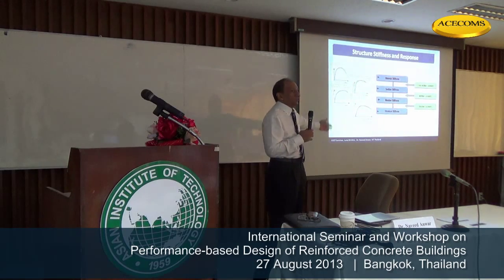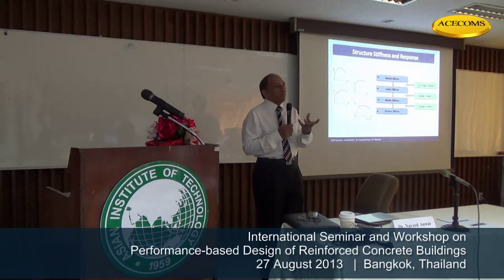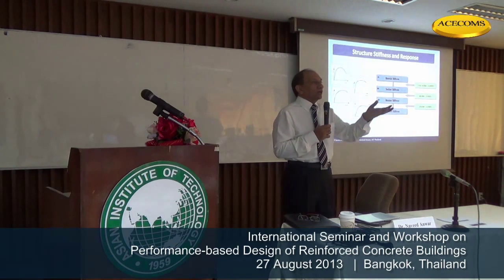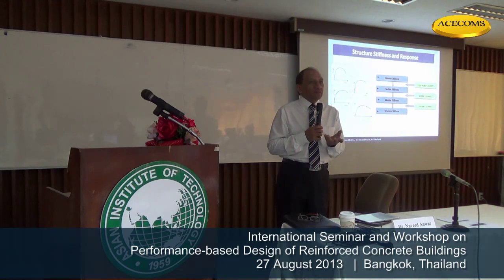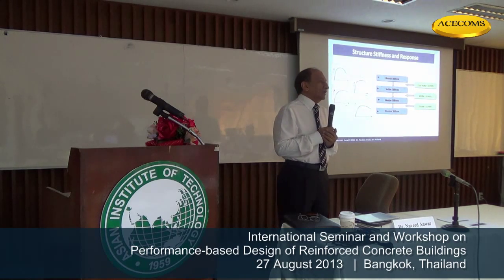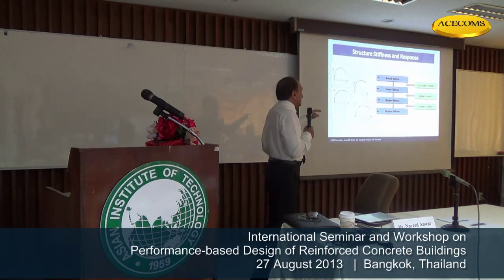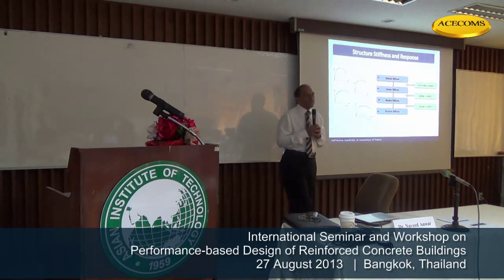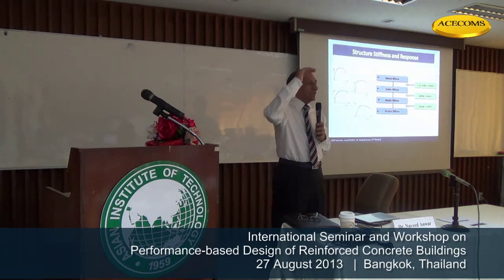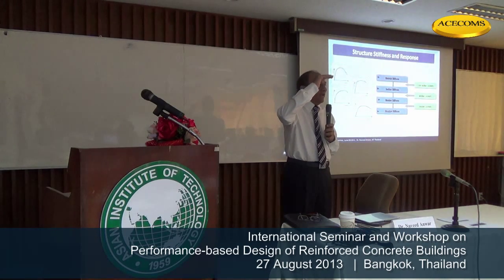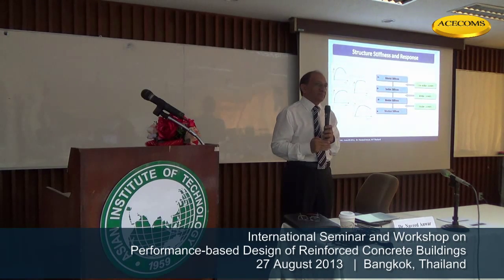Then you have structural stiffness, which is a summation of many members. But some members are collapsing during deformation. Some are becoming ineffective. So the structure is also nonlinear. So structural stiffness K that we saw in the previous equation is highly nonlinear because 4 levels of nonlinearities have been added: material, cross-section, member, and structure.